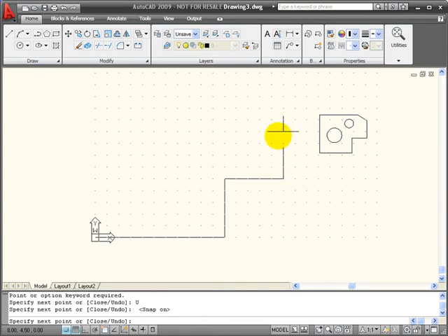And now I'm moving up. This time I want to move up. I know that's 90 degrees. I want to move 3 units. I'm going to use a relative polar. So I will hold down the Shift and use the @ symbol, which is on top of the 2 key, and I put the distance, which is 3, and then I'm going to say angle of, and the open side of my bracket always goes towards the angle, and enter 90 degrees. I'll hit Enter on the keyboard to enter that point.